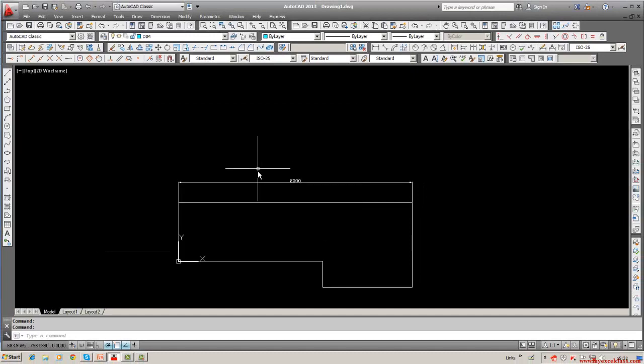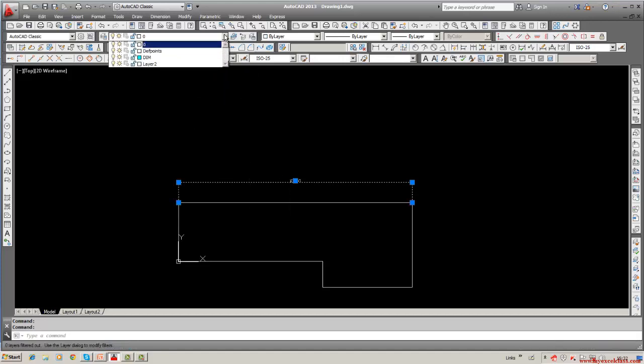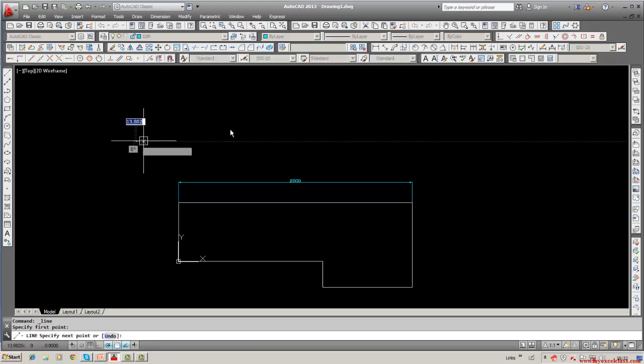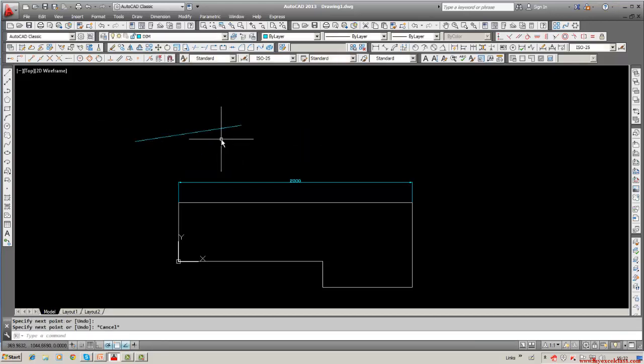So what you have to do is click on this. Click on this, it is 0 layer. Once you click, this is selected, and click here, and click on DIM. So the layer is dimension. Okay, now suppose we draw, see here, ensure that the layer appears here. When you want to draw a line, the layer on which it appears is the layer of that line. Suppose I draw a line here. So it is DIM layer.